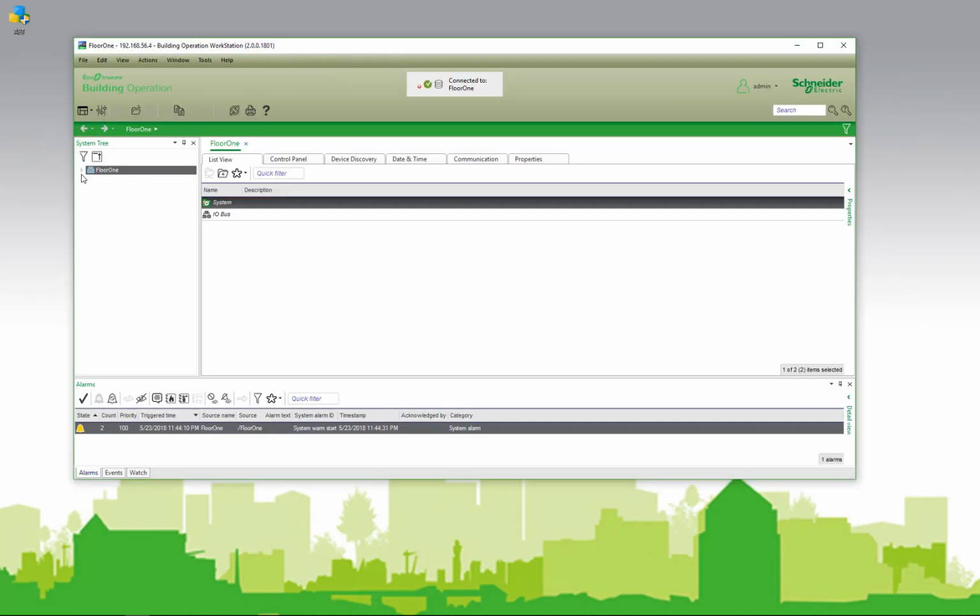So now our virtual ASB is open. One thing that I'll have to do is create a BACnet interface. Under this air handling unit, we're going to have the 10 VAV controllers. Those VAV controllers are the SmartX MP IP controllers. In order to add them here, I need a BACnet interface.